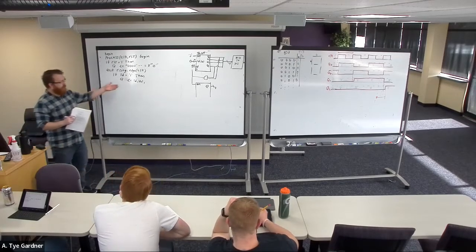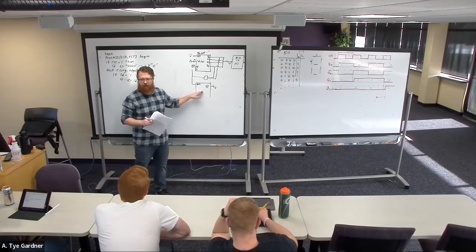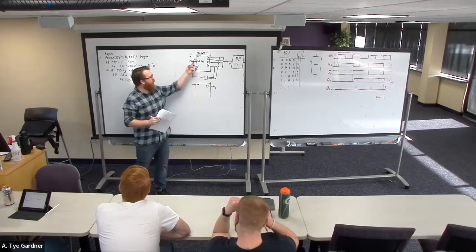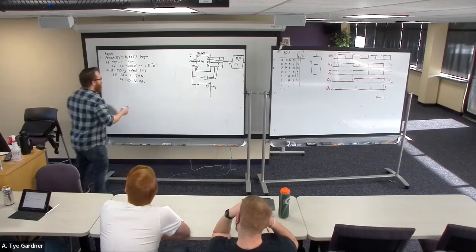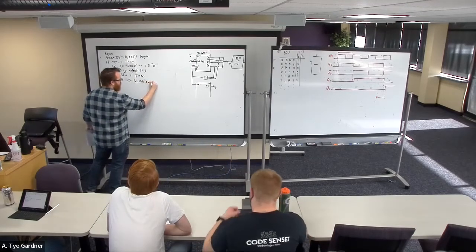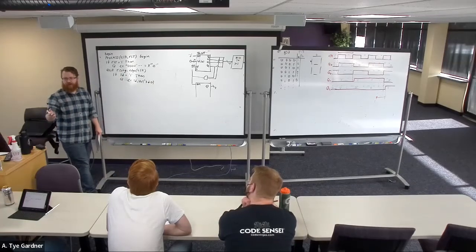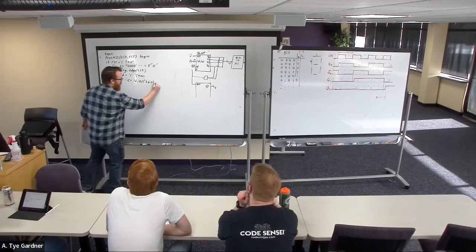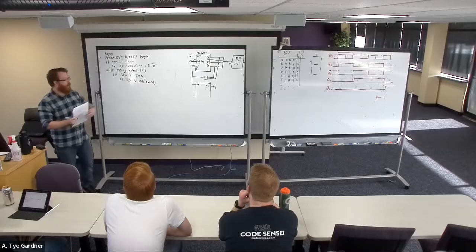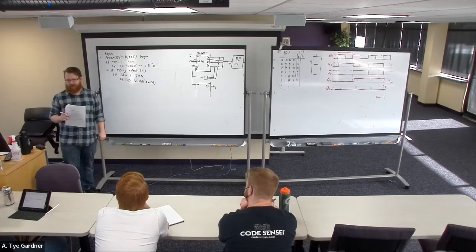So if I built these both into one component, and the load val was an 8-bit input, then I would need to do something like load val 3 down to 0, right? Take the smallest bits of load val. However, this is allowed. If load val is 4 bits, that's 4 bits. This is still okay. It's not wrong. It's just extra writing, right?